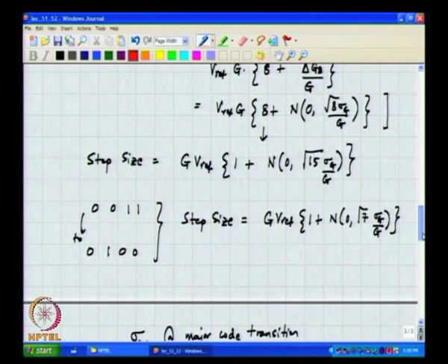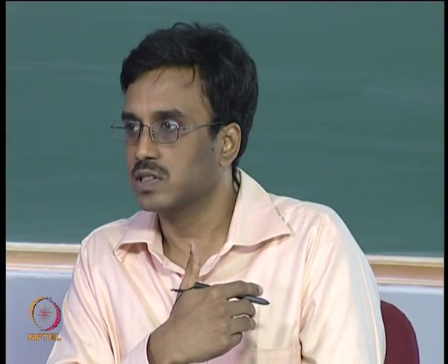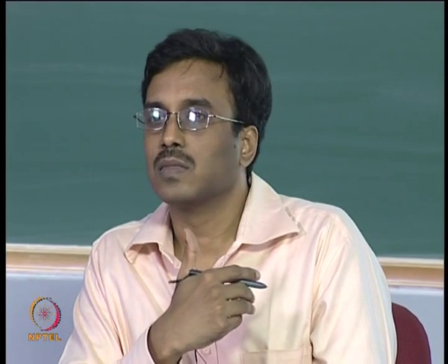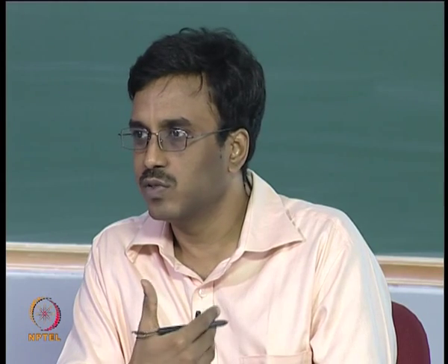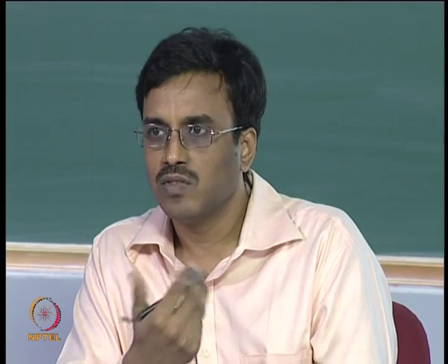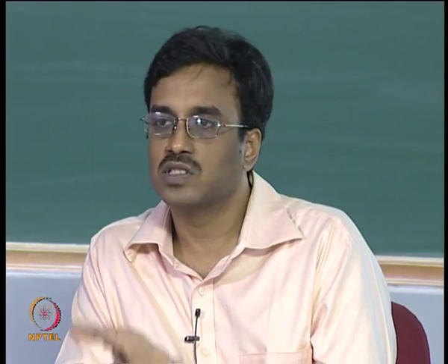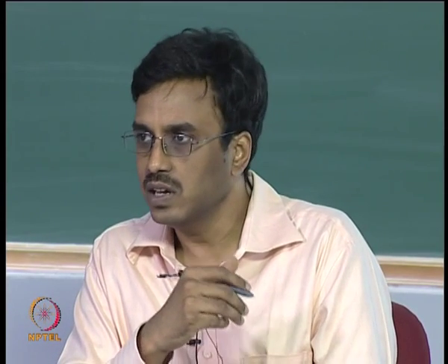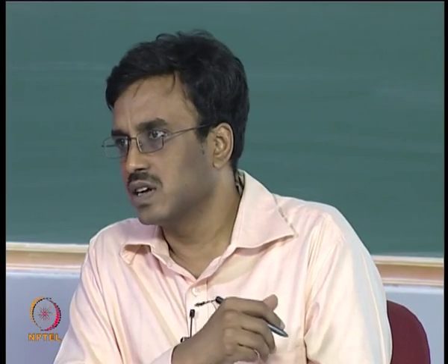By definition, it is the deviation from the ideal. Yeah, it is the integral of the DNL, that is true, but in this particular case it is much easier to find. We know the actual output, we know the ideal output, the difference should give you the INL. Of course, because the levels are statistically varying, it means that the INL is also varying statistically.